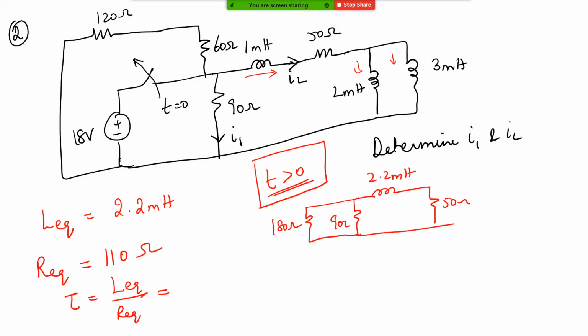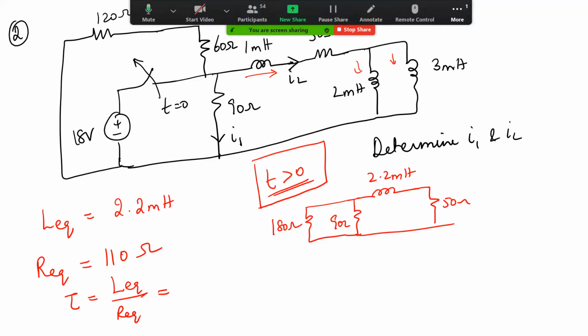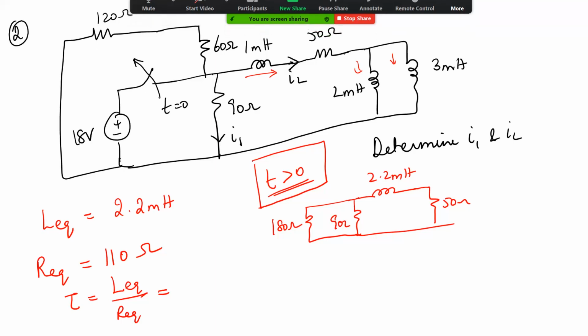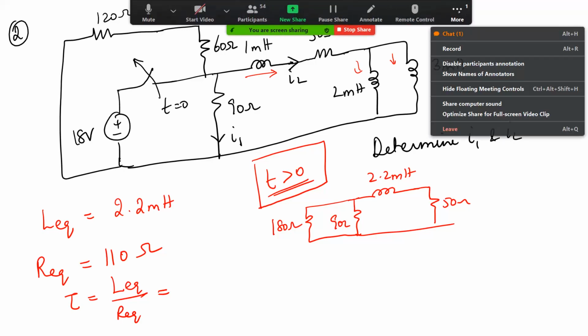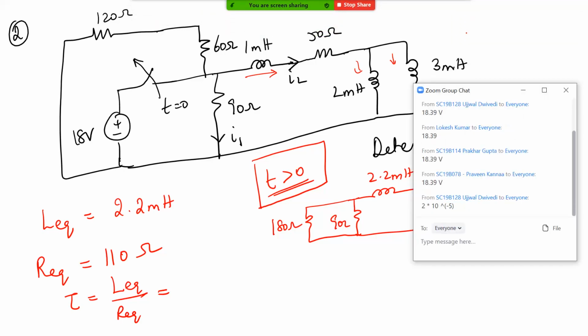But after t equal to 0, that is where the transient response comes. Transient meaning that is where this e power minus t by tau type response comes, and in that case the voltage source is not at all in the picture. That's why I specifically mentioned this is the equivalent circuit after t equal to 0. Is this making sense? Yes, sir.